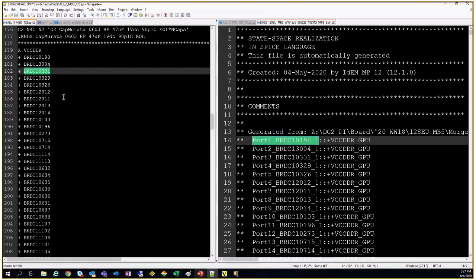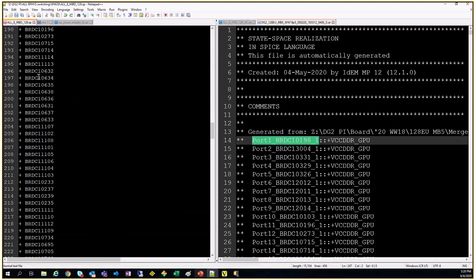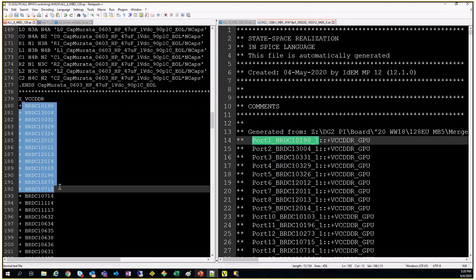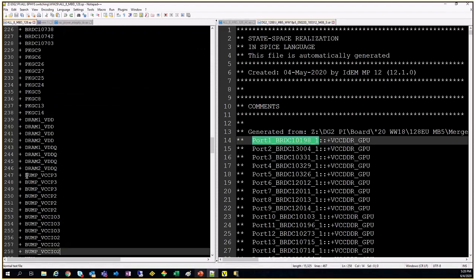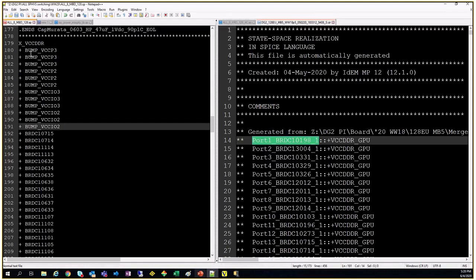Imagine you start with the bump ports. We take Control X and put the bump first over here. Then whatever S parameter is being assigned for the capacitors will get assigned to the bump, which is wrong because the values are different. The bump is at a different location in the PDN network, so it will have a different value. So this order is important.